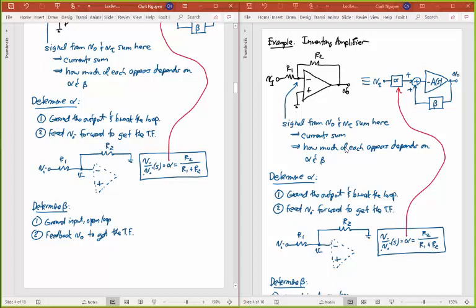And pictorially, what this is going to look like is this. So here's my op-amp, which I don't want to consider here, but I at least want to show you where things are in this whole picture. And so the output now, I'm just going to drive with V0. And that's resistor R2. I have a resistor R1, which used to have an input here, but I'm going to ground that now. So it's kind of like determining an output resistance, but not really. This time, we're determining a transfer function. This node right here is V minus, of course.